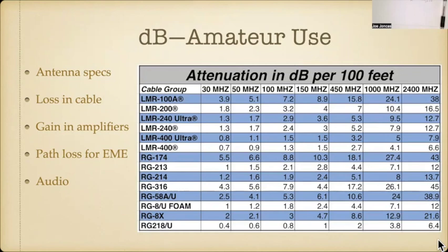That was Don, right? Don, then you made that statement. Why are you insisting on using the LMR 400? Because it's low loss for the satellite frequencies and it's low loss for everything. Yeah, it is. Correct. And look at the LMR here. Here's LMR 400.